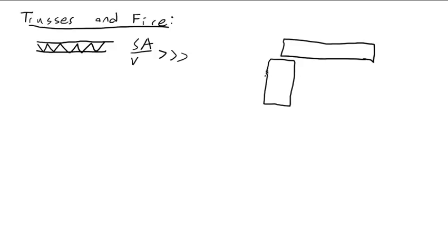Even if you burn through an inch of it, it's still got 98% of its capacity or something like that. This thing burns, yes, but it burns incredibly slowly. You've all experienced campfires and fireplaces. It takes a long time for fires to burn through big hunks of wood, doesn't it? So big, heavy wooden beams actually burn quite slowly. It takes a long time for the fire to reach all the way through them.